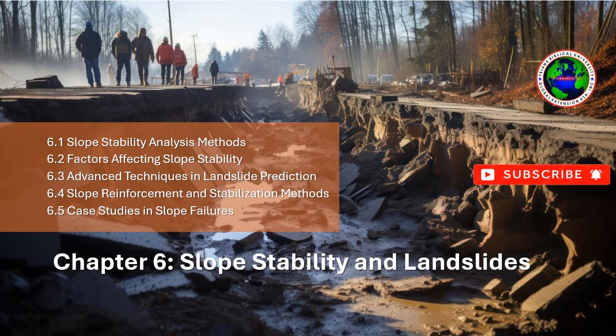Sheet pile walls. Made from steel or concrete sheets, these walls are used in situations with limited space or high water levels, where gravity walls may not be practical. Reinforced soil walls. These walls combine soil reinforcement materials, such as geogrids, with a facing to create a stable structure.